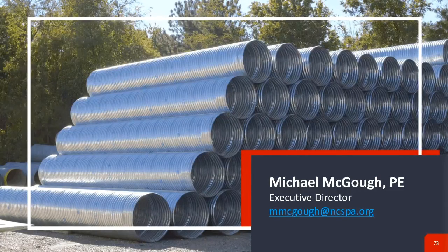What type of coating do you recommend for high abrasion and acidity? Asked Edgar. Edgar, that's polymer. Polymer would be your coating of choice in that particular case. Neither galvanized nor aluminized type 2 would work in that scenario.